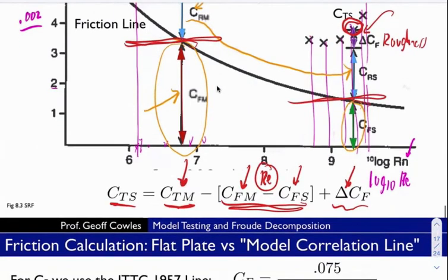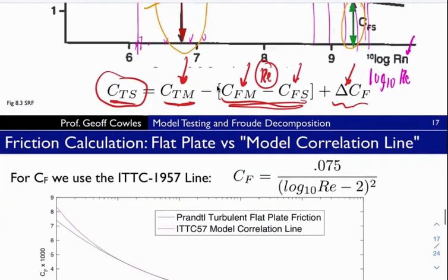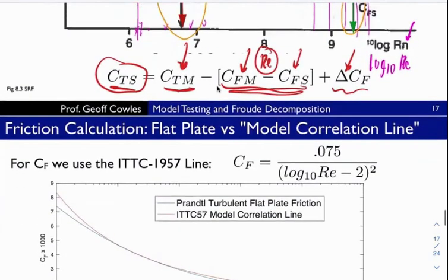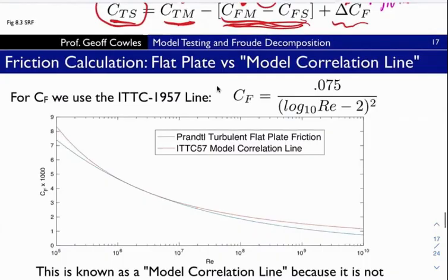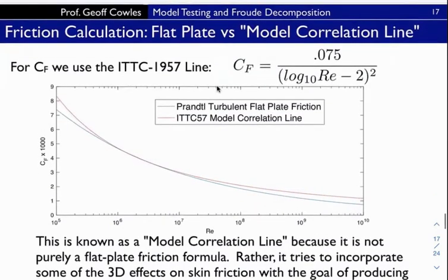And we have the total drag coefficient for the full-scale ship, and that we can convert to a total drag for the full-scale ship. Now, some caution here. These frictional drags for these methods that we'll be talking about, these ship extrapolation methods, do not use the flat plate Prandtl curve that we've been using. They use a slightly different curve, which is known as the ITTC 1957 line. This, again, is the International Towing Tank Conference, I believe, 1957 line.